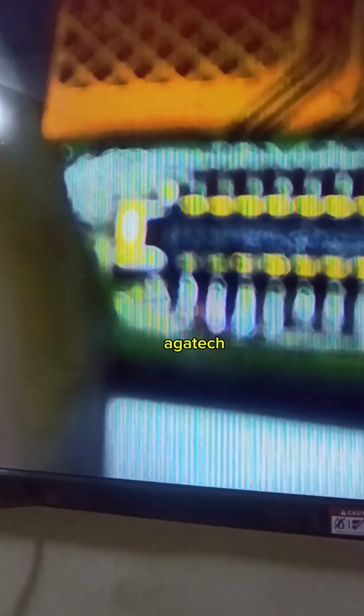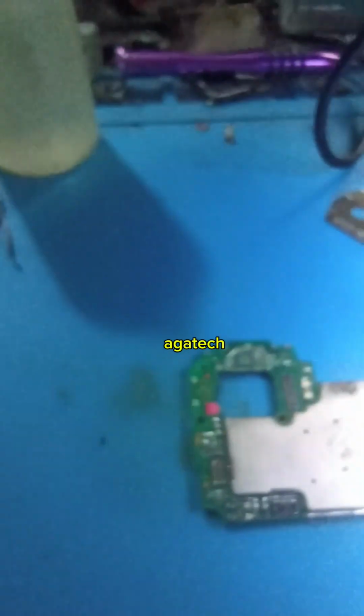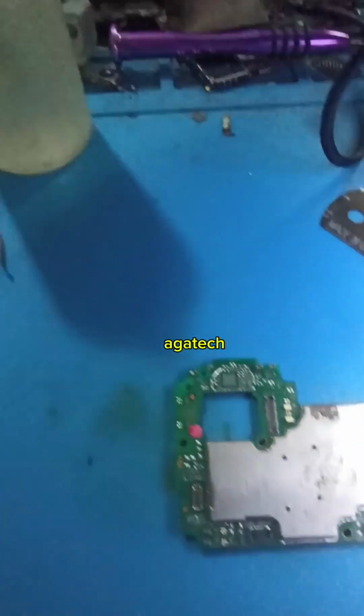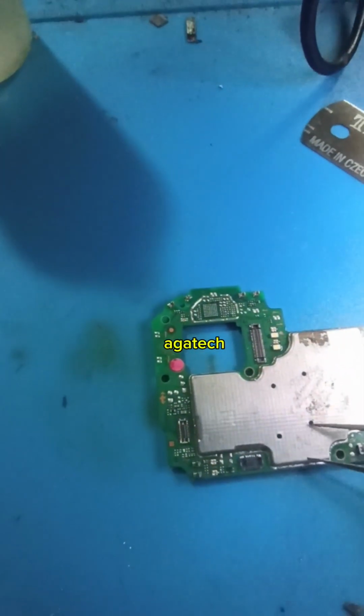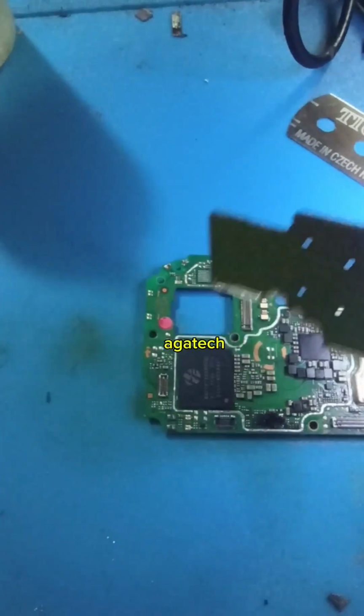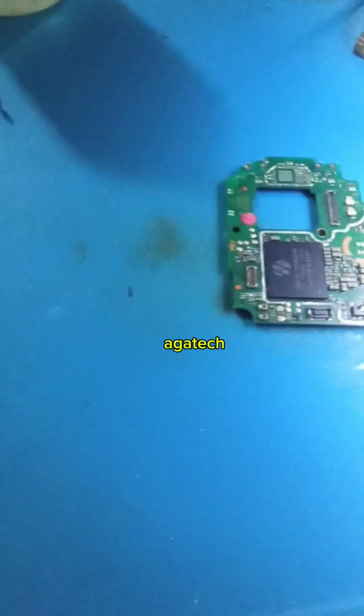You can see those two pins have spoiled, so I fixed them too. But after fixing it, I discovered that the backlight still did not work. So what's next? I decided, okay, let's check the backlight circuit, and I opened the metal shield that covered the backlight circuit. So this is the backlight circuit.